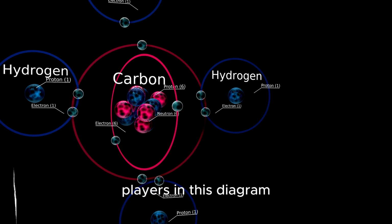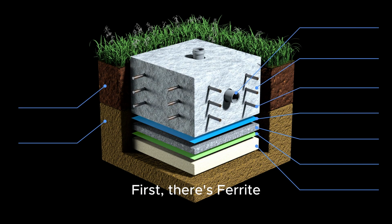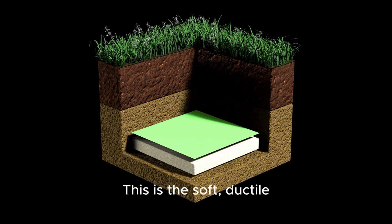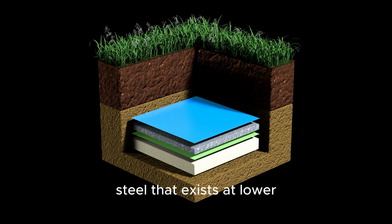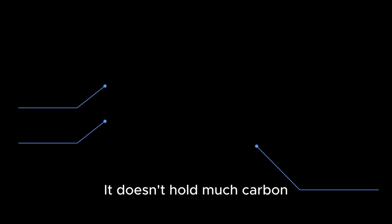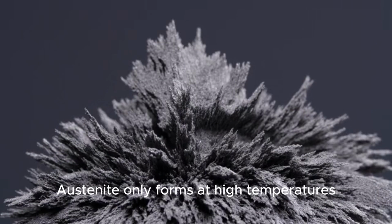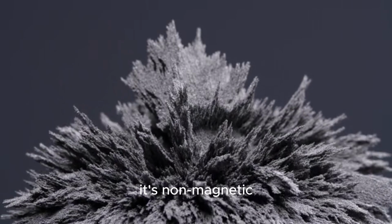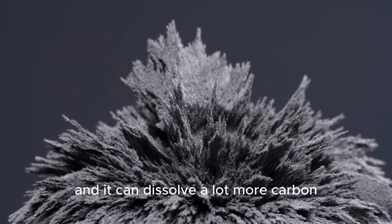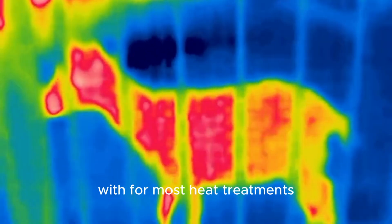Let's look at the key players in this diagram. First, there's ferrite. This is the soft, ductile, magnetic phase of steel that exists at lower temperatures. It doesn't hold much carbon. Then we have austenite, the star of the show. Austenite only forms at high temperatures. It's non-magnetic, and it can dissolve a lot more carbon. This is the phase we start with for most heat treatments.